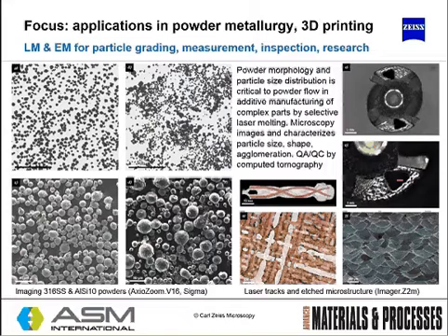So powder metallurgy is used for near net shape manufacturing. It can be, but is not necessarily, porosity free. And the quality of the finished part depends on the particle size distribution and sphericality of the powders themselves. And with a modern light microscope, you're able to perform this analysis completely automatically to do the particle size distribution, and you can calculate the weight percent.